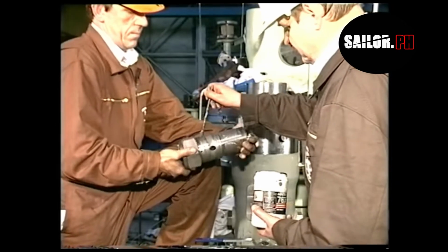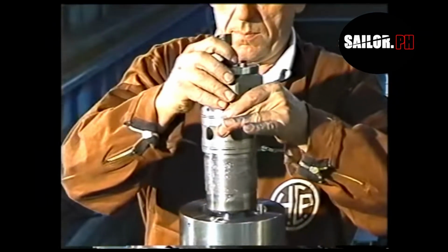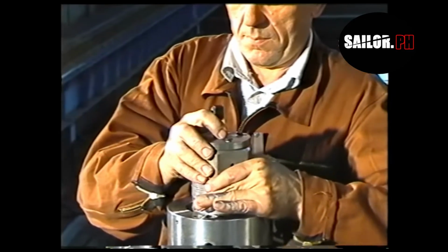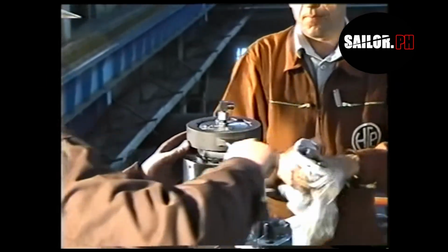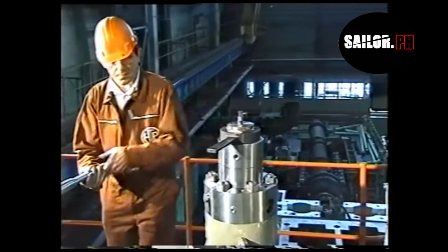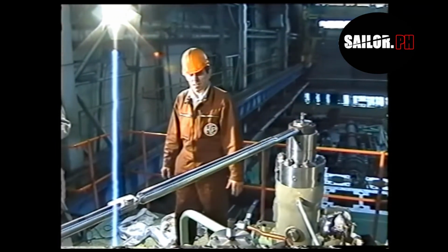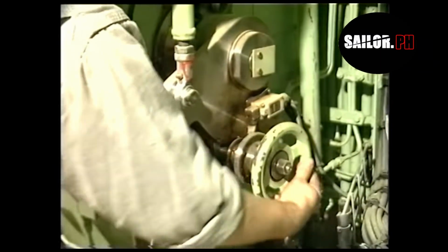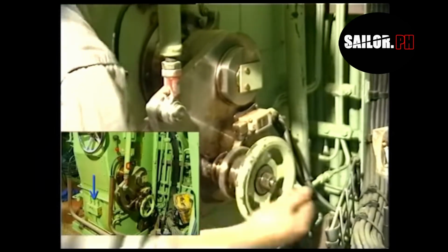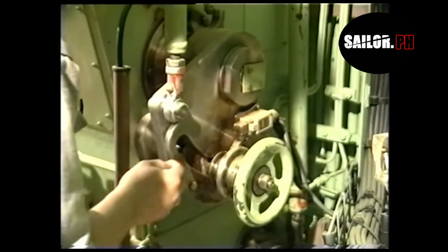Provide the puncture valve with new sealing rings and lubricate with molybdenum disulfide. Tighten the puncture valve to the torque stated in the instruction book, Volume 2, Chapter 909, and mount the plug screws, cover and control air pipe. Finally, change over to normal engine control. Make sure that the VIT system changeover valve is properly connected.